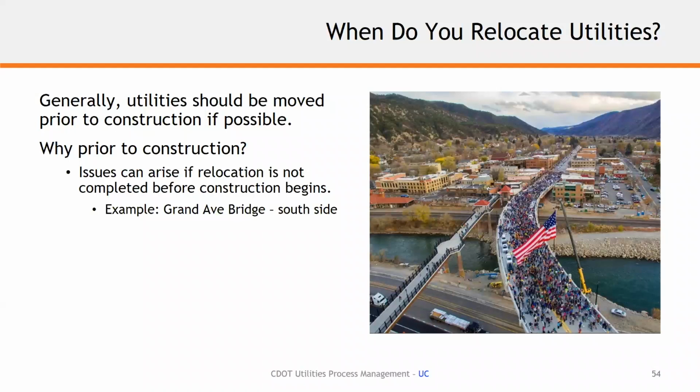If there's not, then we'll include it in the work or identify it and give contractors notice and put it everywhere we can, so that as a contractor coming into the project, they have the opportunity to know what the risk is from a utility standpoint and what they have to deal with, like you said, with third parties working on top of them. There's a lot of effort that has to go in with multiple contractors on top of each other. There's traffic control issues, there's stormwater quality issues when you have utility contractors working on top of the CDOT contractors. So a lot to consider.